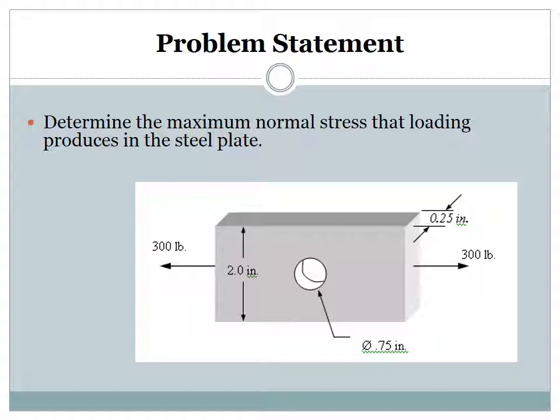Now, I'm just barely scratching the surface here, but I do want to give you an idea of what SOLIDWORKS can do for you via the Simulation Xpress. In the unit demo, I'll model this part for you and show you how to do a simple force simulation. You should be able to replicate this on your own system. If you have problems, let me know. So here's our simple problem. Determine the maximum normal stress that loading produces in this plate.